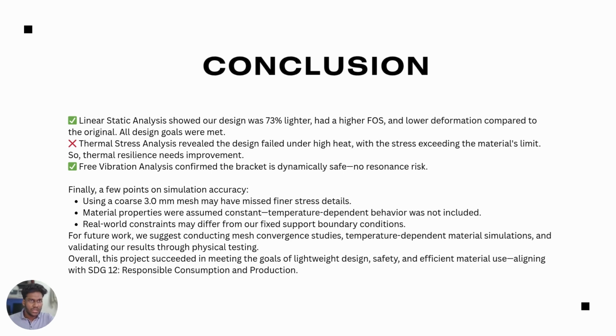Finally, the 3.0 mm mesh may have missed finer stress details. Material properties were assumed constant; temperature-dependent behavior was not included. Real-world constraints may differ from our fixed supports. For future work, we recommend conducting convergence studies, temperature-dependent material simulations, and validating our results with physical testing.